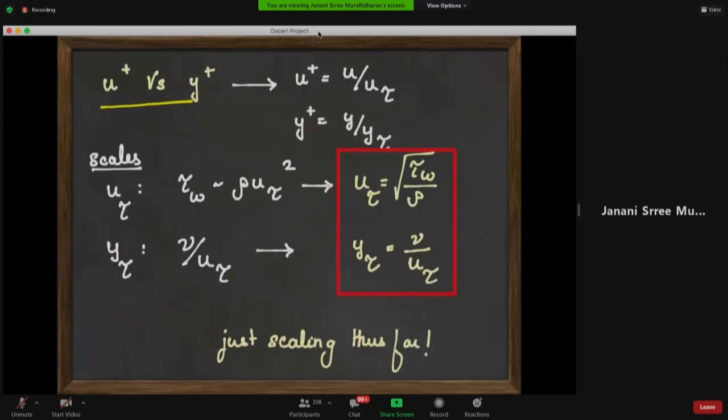Let me tie it into the OpenFOAM part of it. I mentioned that the velocity you see in the experiment that I am running, and in the experiment that Ashley or Divyesh are running, needs to be a non-dimensionalized version. So I have to make velocity and distance something that can be non-dimensionalized. You have a U tau and a Y tau, which are used to non-dimensionalize the velocity and the distance. Somebody has to come up with what this parameter is, correct?